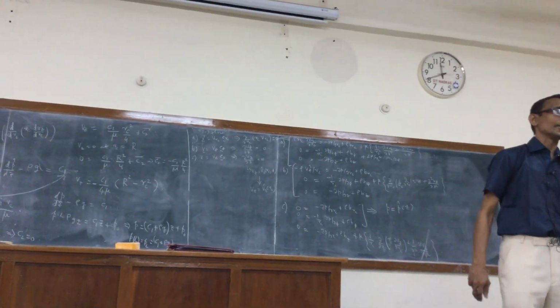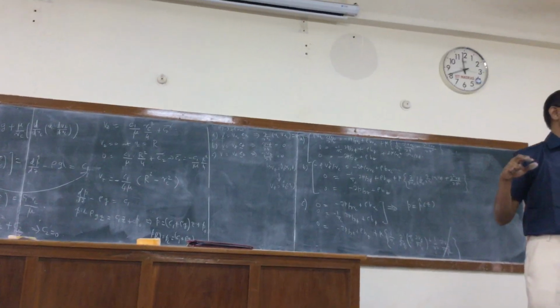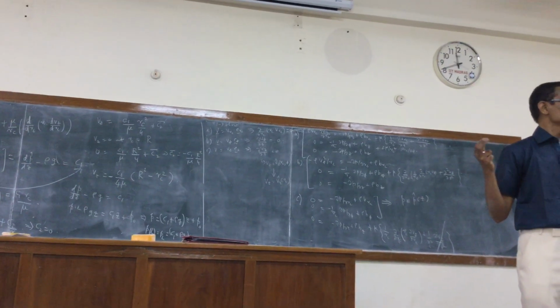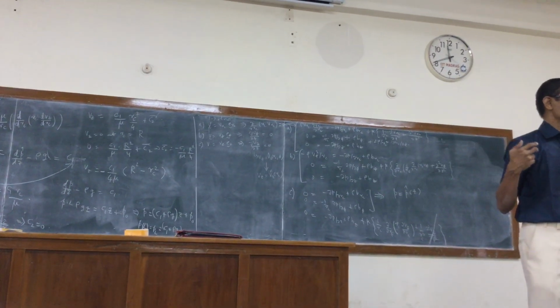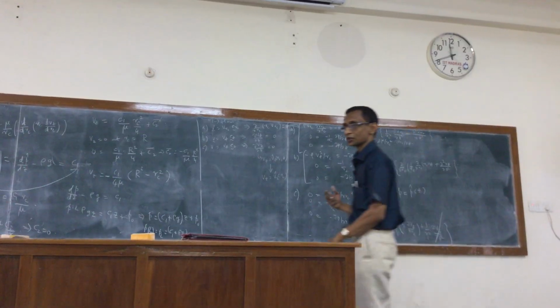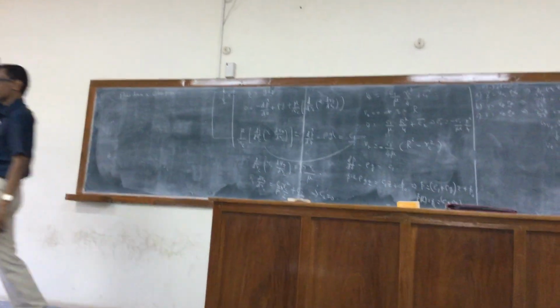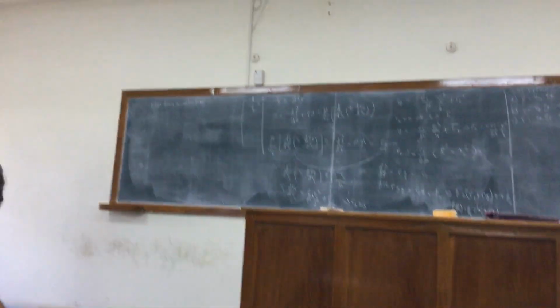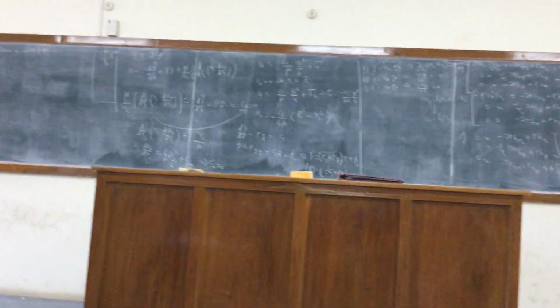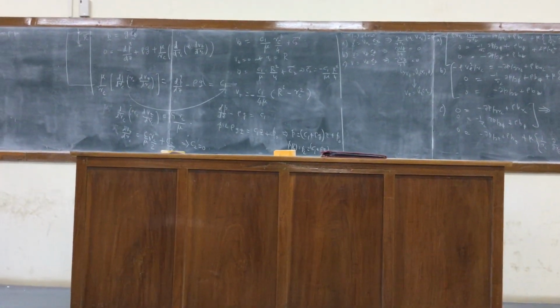So we now see that to determine C1 unambiguously, we need to know the pressure actually at 2 points. So there is an integration constant coming from the pressure, and 2 integration constants coming from the velocity integration. So the total 3 constants have to be determined, right?